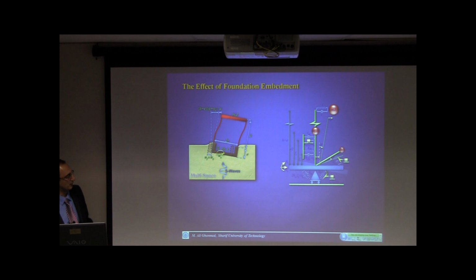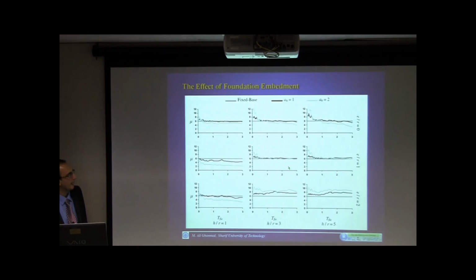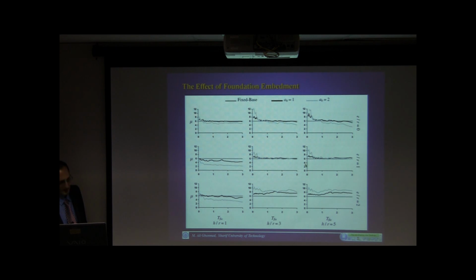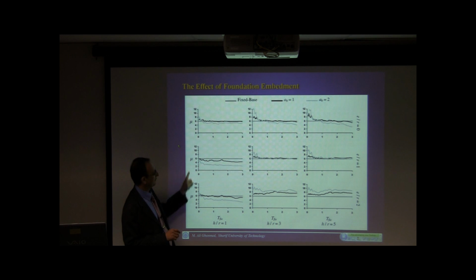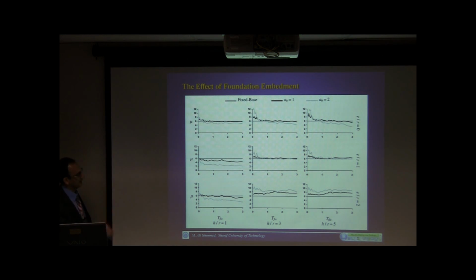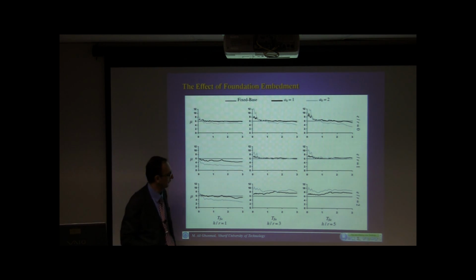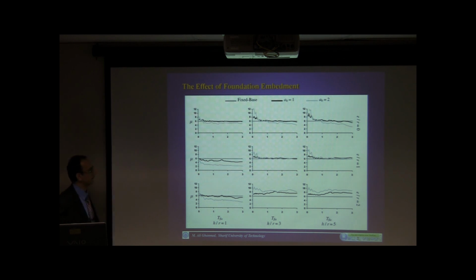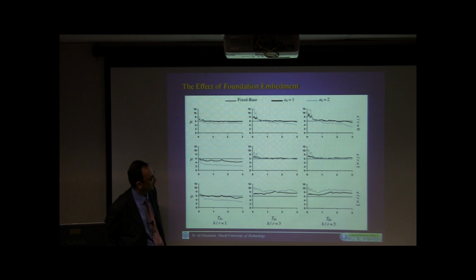Here we used the same model of Wolf and Meek to compute these foundation input motion elements. And this is the result, some examples. Again, here we have ductility demands for different aspect ratios in different columns. And 3 cases, I'm sorry, I didn't have the color graphs for the figures available. For the fixed base, A01 and A02.